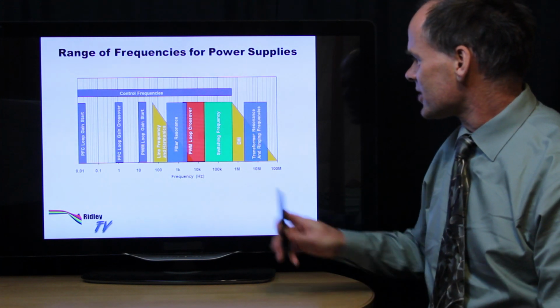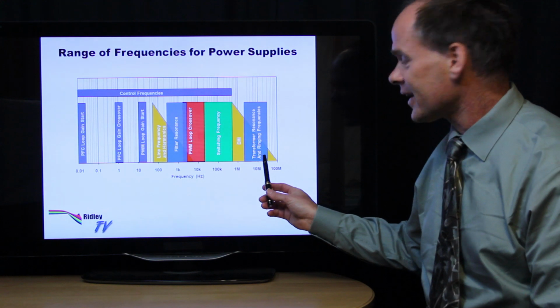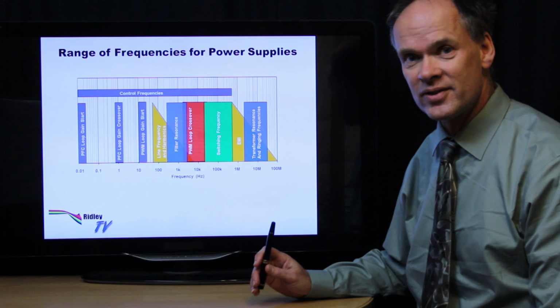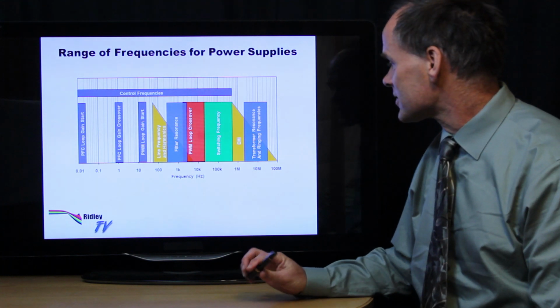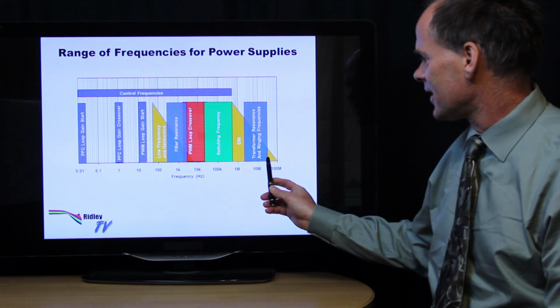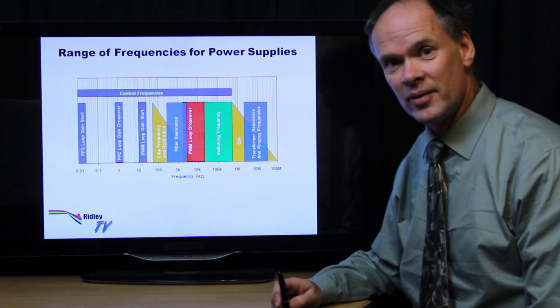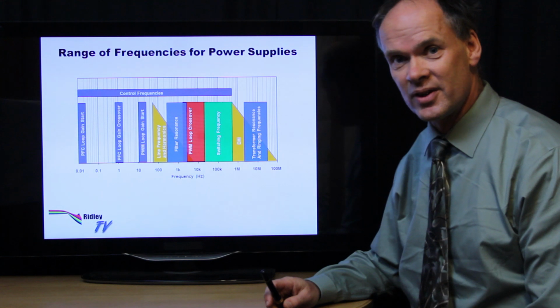We also see transformer resonances and ringing in our power circuits that we have to measure and characterize and design around. So it's very important when we have a frequency response analyzer that we can pick up the characteristics of our magnetics here, because that will enable us to do the snubber design of the circuit.